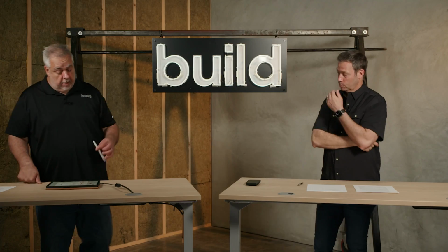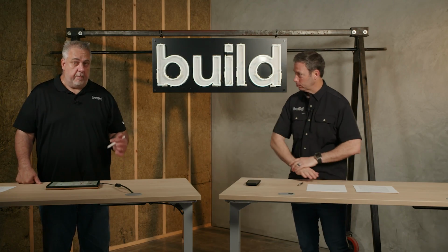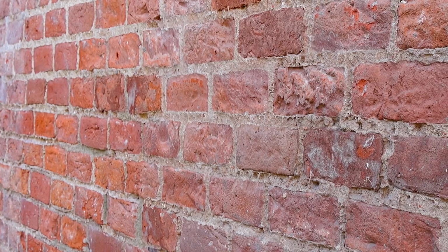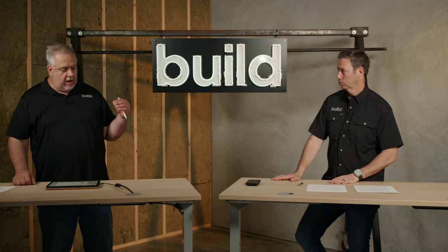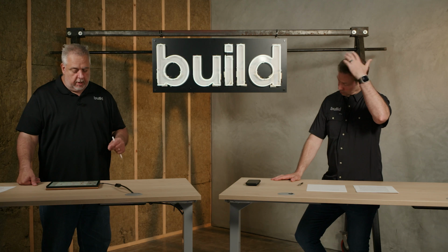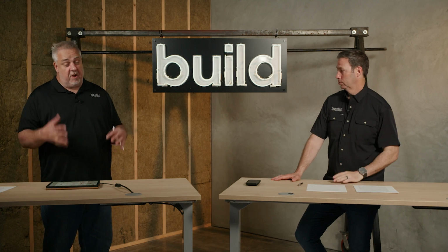Yeah. And you bring up a good point about the brick and stone. But the thing about brick, stone, all of that, guess how they're attached? They have mortar joints. Mm-hmm. That mortar joint has a very high level of risk. We actually did a test. We were doing a building investigation, and we turned on the spray rack and went inside to see how long. It was something like less than 90 seconds. We had water coming through the backside of that mortar joint. Holy cow. Like it was just sucking up the water. So it's in effect a big sponge on the outside of that.